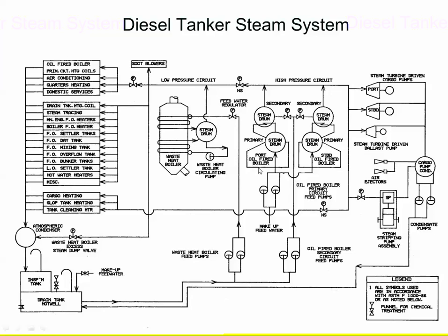This is your high pressure, like 1,200-pound boiler, producing saturated steam that goes through a heating coil in the secondary steam drum, which they call a steam-to-steam generator, and then it flows back into the oil-fired boiler steam drum again. Natural circulation here, right? The steam goes up, and this steam drum is probably within 5 feet of the oil-fired boiler steam drum, so these lines are fairly short.